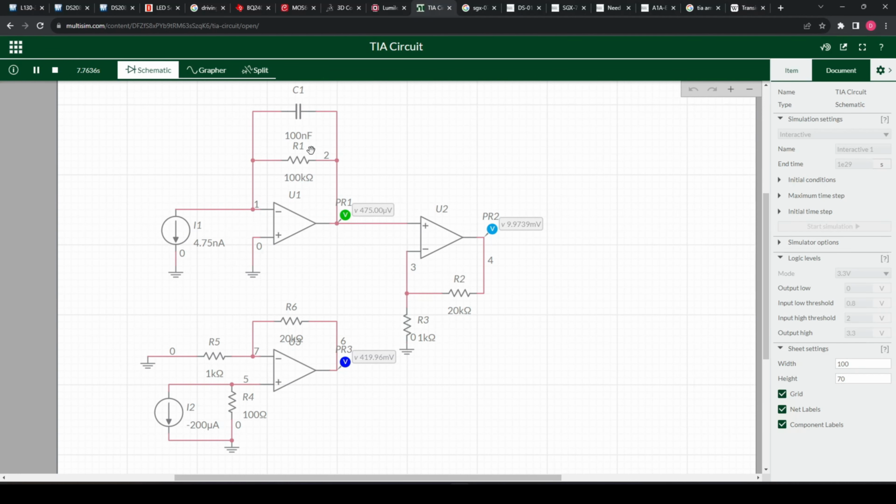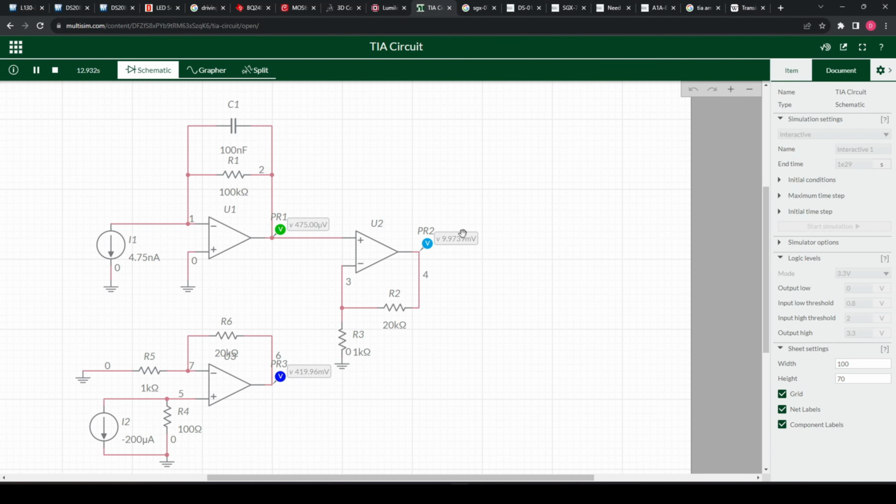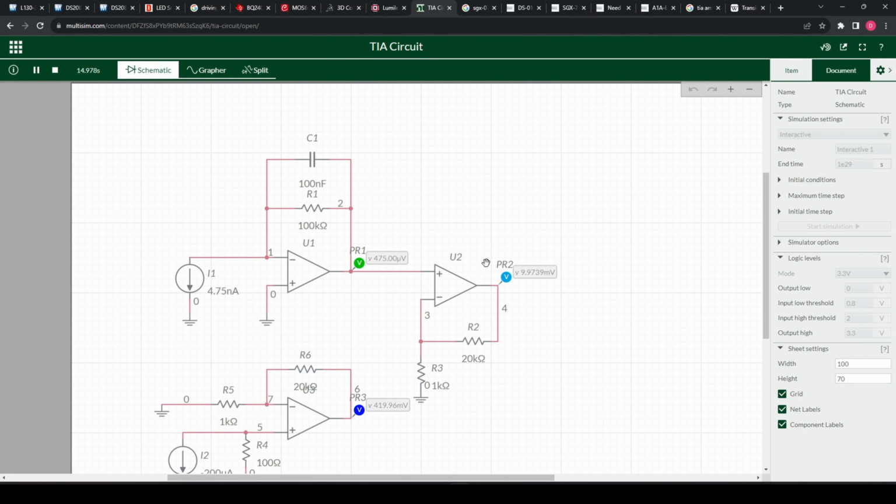Again, the gain isn't too much, and usually you would have a 2-step or 3-step sort of gain amplification, then you would put this through to a more readable voltage level. So here we've got 20 times a gain, or 21 times in that configuration, I suppose, and we've got nearly 10 millivolts. And again, you would feed it through here to your microcontroller to suitably max out at 3.2, 3.3 volts. So this is sort of how you would design one around this kind of angle.